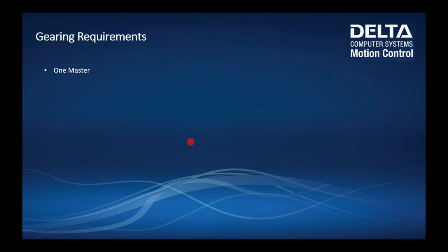Okay, so what are some gearing requirements? Well, just like we said before, you're going to have one master. Another requirement that we will talk about here, and we can kind of see some of the results from, is we want a smooth target. So a lot of times with physical axes, say you've got two cylinders and you want these cylinders to be synchronized together. If it's just a one-to-one relationship, a lot of times not a gearing command, but just a simple move absolute is even the best way to go.